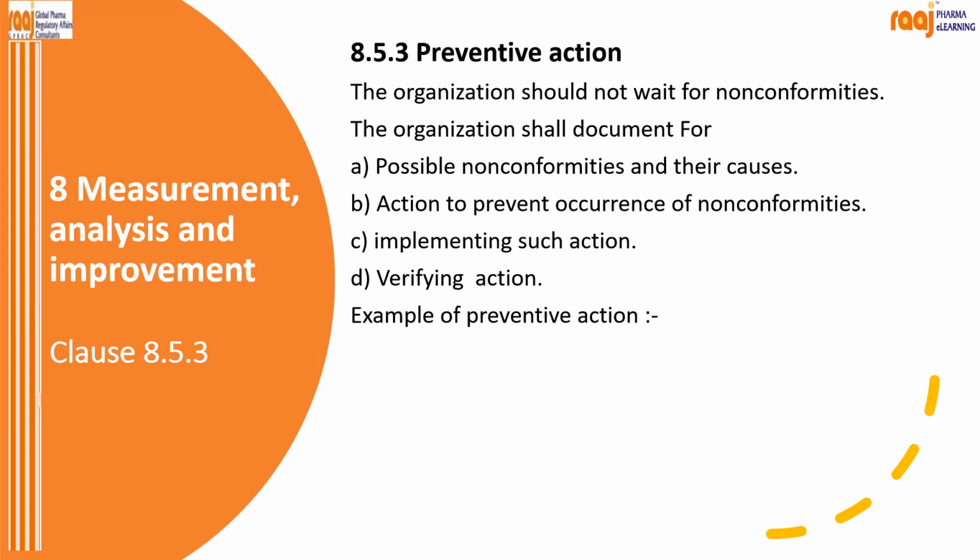A camera is sometimes installed, and sometimes they install a small fan so that if the blisters are empty, it will blow out all the tablets, and rejection will happen automatically. That's a rejection mechanism. So you can see what technology is best to identify those gaps, and accordingly you can implement it and take the action.